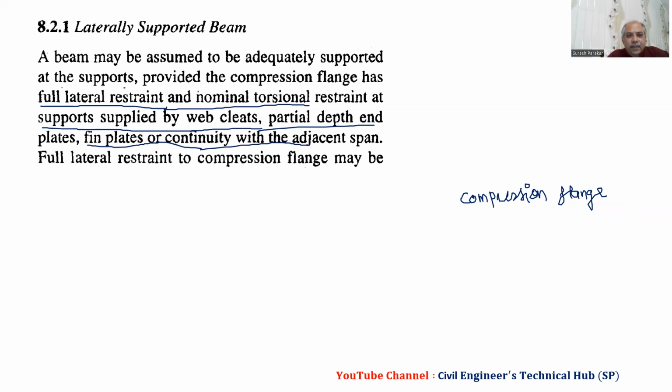So whatever is mentioned over here is related to supports. But full lateral restraint to the compression flange may be provided. Means if my compression flange is laterally restrained, then I will say it is a laterally supported beam.